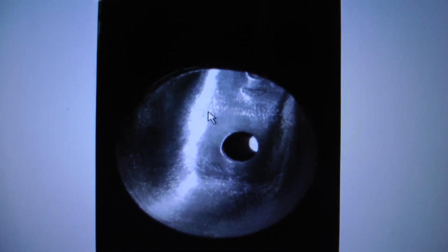I think the rule is about 85% of your valve face. You don't want to go really beyond that because you'll lose velocity. Now keep in mind, velocity and even CFM are the voodoo portion of engine modification. You could still have a faster car, and it really comes down to power band as the definitive result. So that's what you really want to look at. So I'm going to close that one.